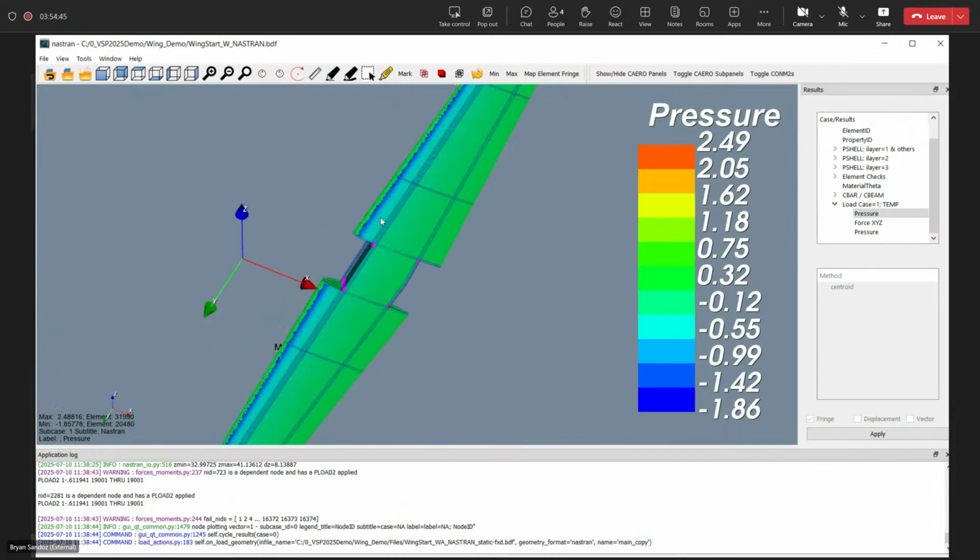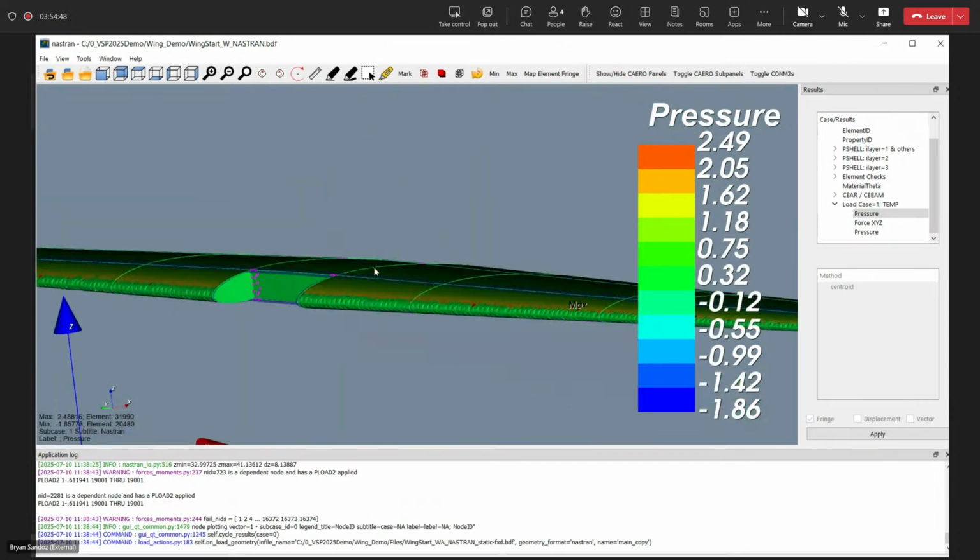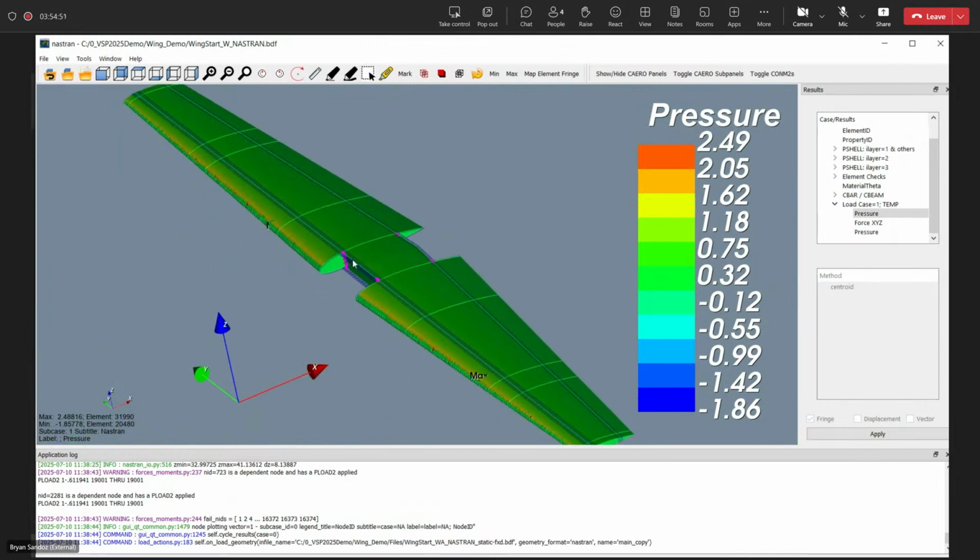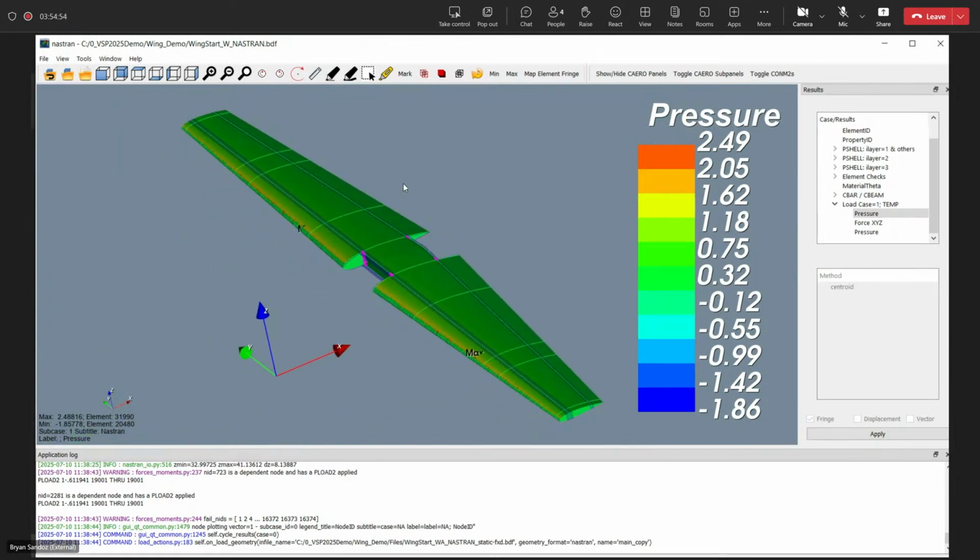And one thing that's of note here, if you've done more of this, I'm using VSP Aero in the VLM mode. I'm doing that because you can then apply representative pressures from control deflections, flaps, and ailerons, and things like that. If you really wanted to do this for a wing and capture that completely, you would want to break out the flap and break out the aileron. If you're trying to do this with the VSP Aero pressure mapping, you would need to model those as separate components and attach them to the wing, which you can do. And I have done that before.